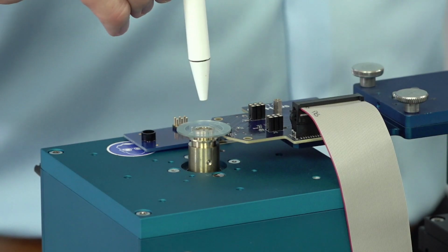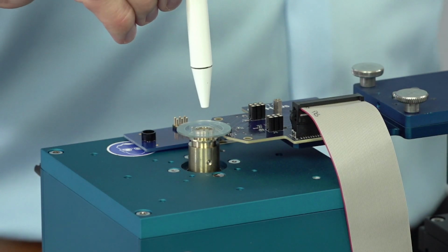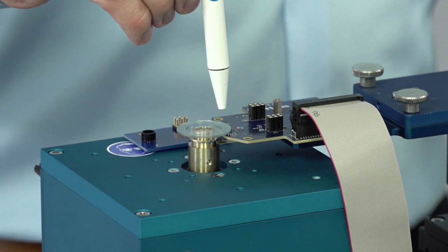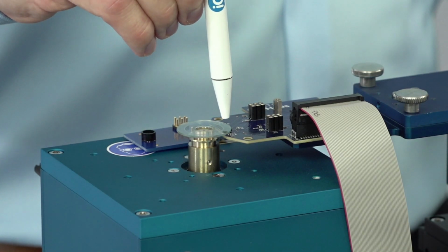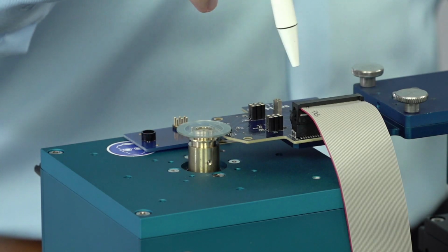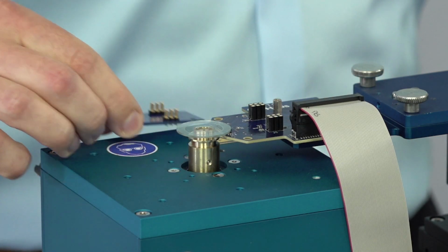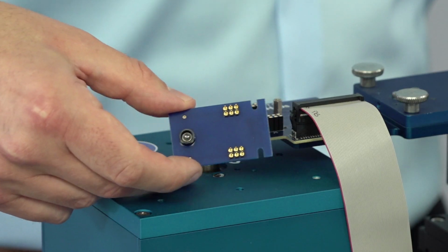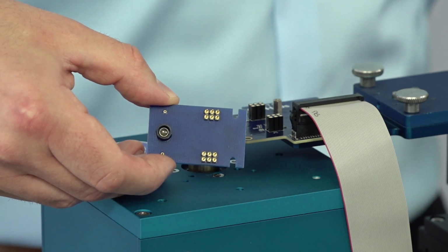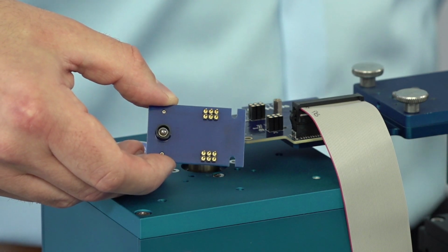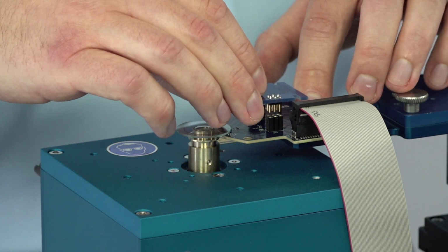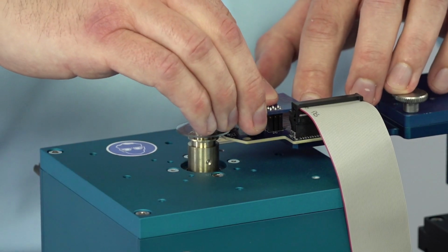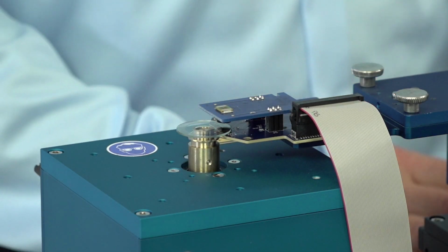So first, you see the code disk, the 26mm code disk here mounted onto a shaft. Underneath the code disk here, you can barely see it, but it's there, is the 5x7mm sensor package. Here's the sensor board that I just showed. And let me show you, just checking if you can see it on the camera. Yeah, here's the LED module, the TL46 blue LED module. And well, I simply connect it onto this sensor board carefully. All right. Things set, encoder stack assembled.